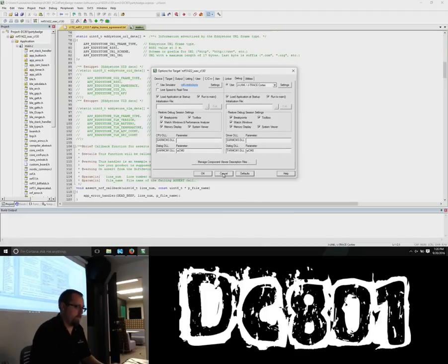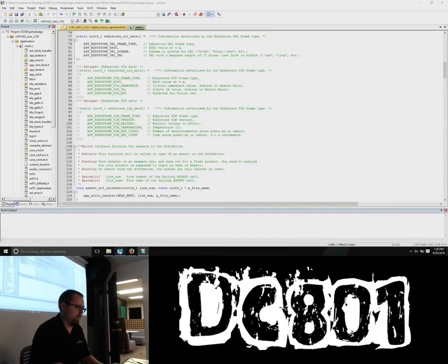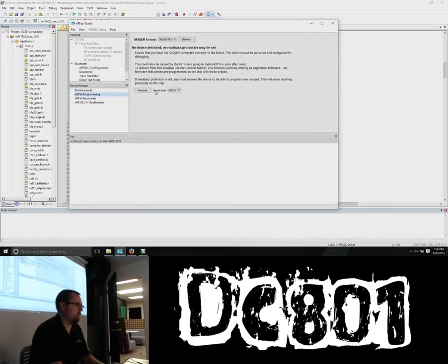So the first thing that you do with nRF Go Studio is flash it. You erase it and then you reflash it. But once you have done it with the soft device the first time, then you don't have to do that anymore on the initial go-through. Or if you mess with your program, you can't brick your device; this is the way that you can recover it, because this will go through and wipe your whole memory.